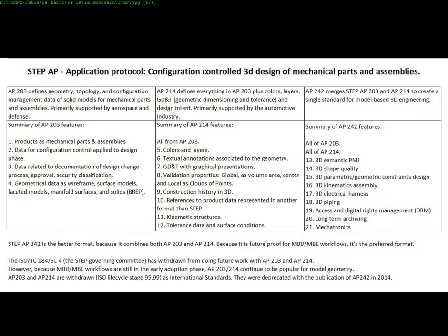At this moment, there are three standardized application protocols, called AP: AP203, AP214, AP242, with features as presented in this table. You can select the right AP for your purpose, or according to import machine specification, from Tools, Options, General, Compatibility, Step tab.